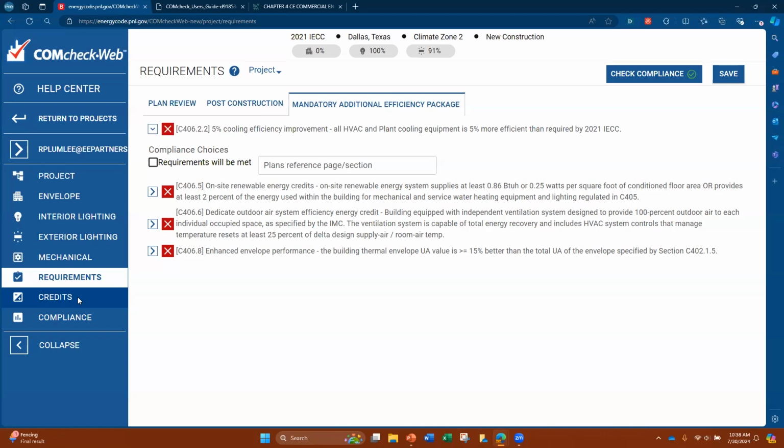One way that we do it in residential is, even if you didn't see it and you didn't actually look at the envelope, once I do a blower door test, it will tell me if that envelope is good. It's going to tell me that it doesn't have holes in it. It's going to tell me that I meet compliance.